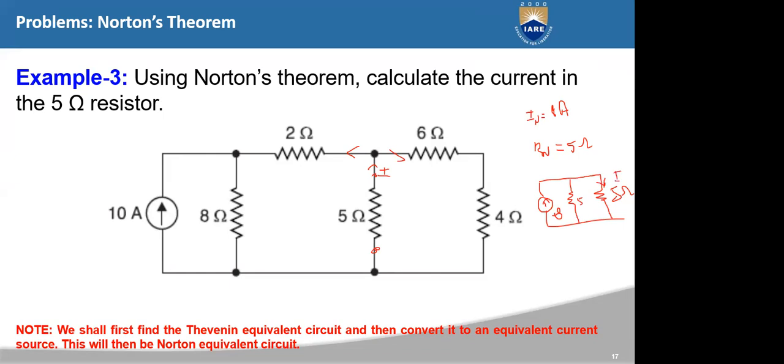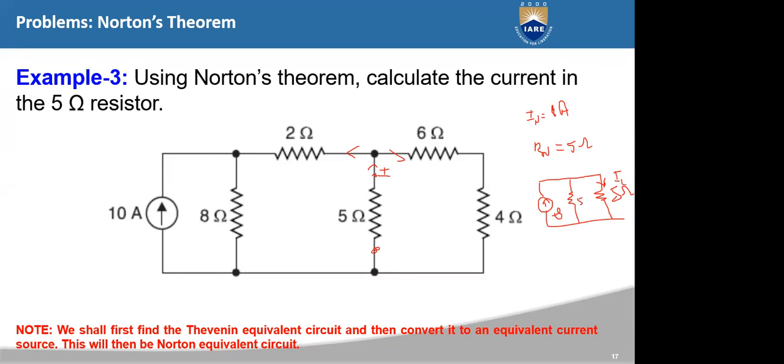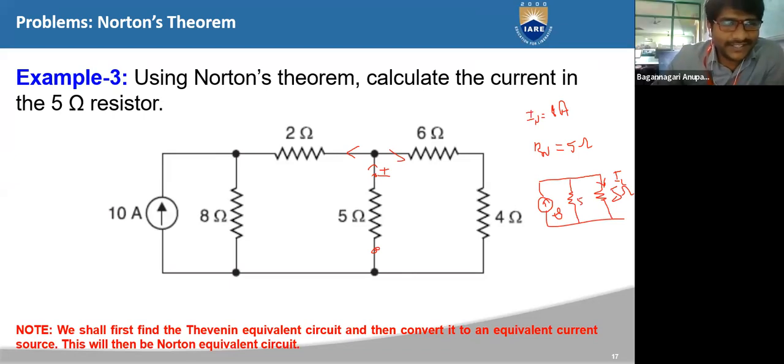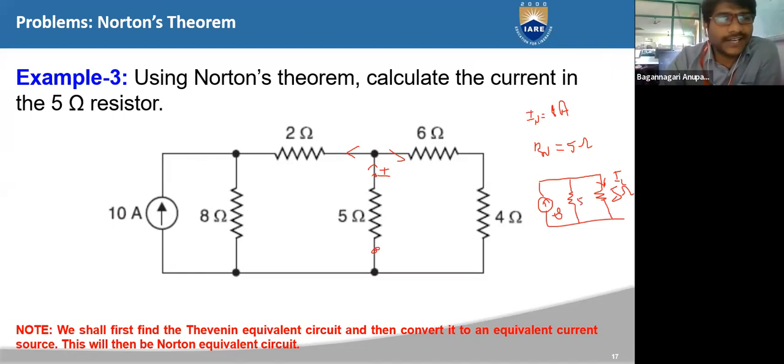What's the equation I write here? IL, as directly I write it as 4 amperes, or is there any equation for IL? We can again use the current division rule, sir. Since the resistances are the same, the current will divide equally. Yes, sir. Fine. So the justification is that since the values of resistors are the same or equal, the current divides equally between them, right?